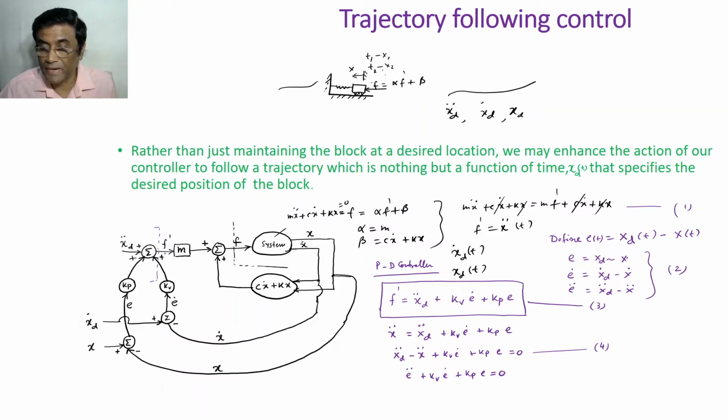Actual value will be obtained from a sensor. If it is a motor, we have a position sensor called an optical encoder. If it is some other device, we may have an accelerometer, position sensor, piezoelectric sensor, lots of other sensory devices. Sensor is a must, desired value is a must. Sensor will give you the actual value. Desired value will be obtained from your planner computer, right? So you can compute error at any instant of time. It's a function of time.